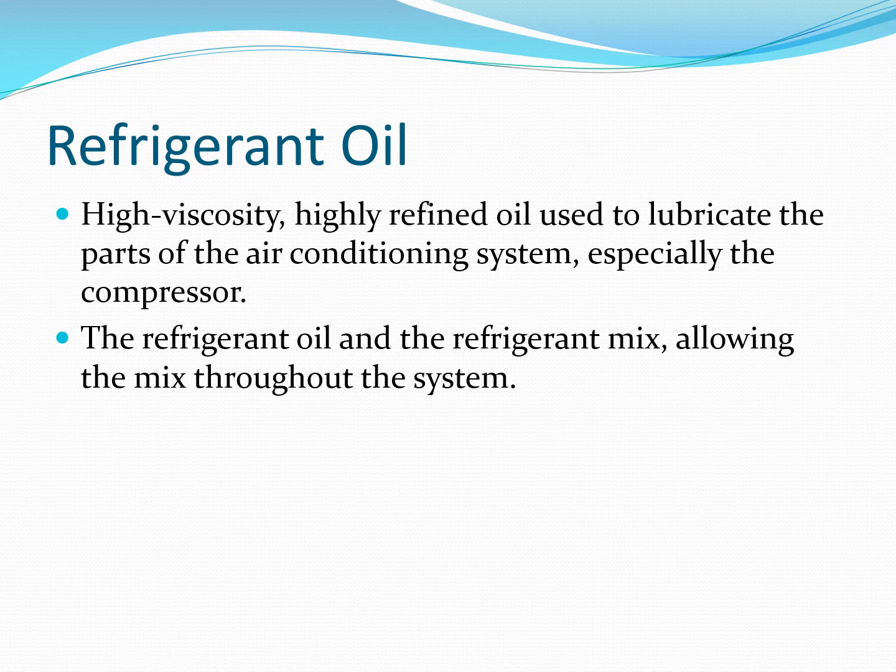But the refrigerant that you're using in the system needs to have an oil that is going to mix with that refrigerant. If you don't, then you have the opportunity to burn something up, and the first thing it's going to burn up is going to be your compressor. And if any of you have priced an air conditioning compressor, you know that these things can get very expensive. It's not unusual to see $300, $400, $500 air conditioner compressors.